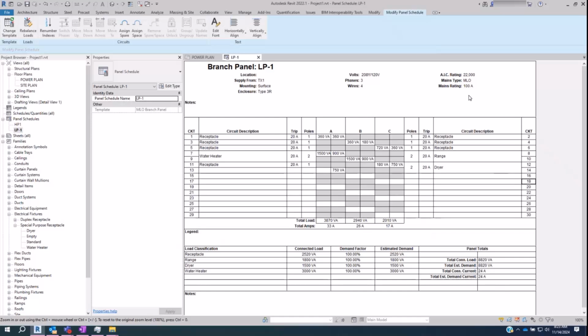So if we put right at 80 amps on here and we didn't want any more on there, then yes, I would probably spread out a couple of the receptacle loads to take up all of the breaker spaces so that they couldn't physically put anything else on here because I already knew they were at 80 amps. That's like 2% of the time. It's very rare. For anything that you are going to come across, it is actually a good idea to leave spaces and spares on there both.